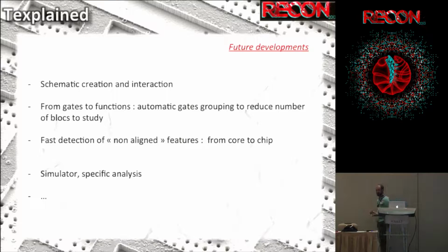For this, there is something very easy, because the software is extracting gates. So it says, for example, I found this type of gate 200 times on the chip. But now you can look at the links between the gates, and you will find that this gate is always linked to this one 5 times on the chip. So they are linked 5 times. It's not something random. It must be a function.